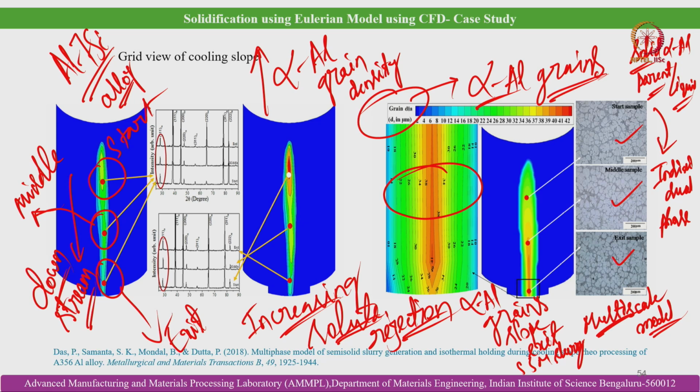You can predict the microstructural information along with the flow physics of the solidifying melt within the component cavity, and also the temperature distribution, and so on, which can give you an idea about the mechanical properties of the component upon solidification. Moreover, you can use the output of this computational fluid dynamics based process model as an input to the mesoscopic models, where you can predict the microstructure, and then the output of the microstructure evolution model you can use to predict the mechanical properties.